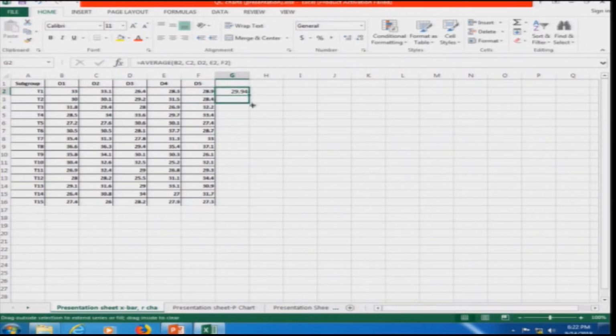Now, I can drag this formula using the small plus sign, which is the selection of the formula. If I drag, the formula is copied and I have got the X bars: X1 bar, X2 bar, X3 bar, X4 bar, and so on.